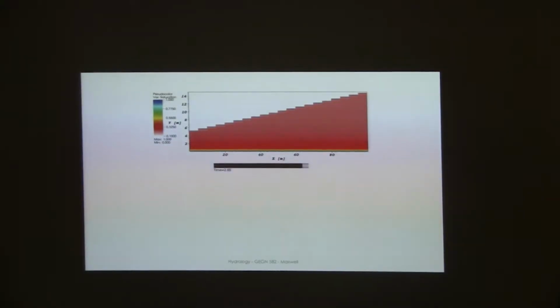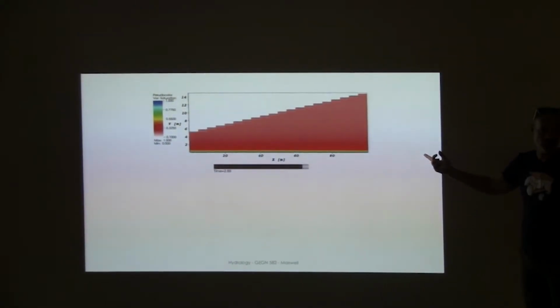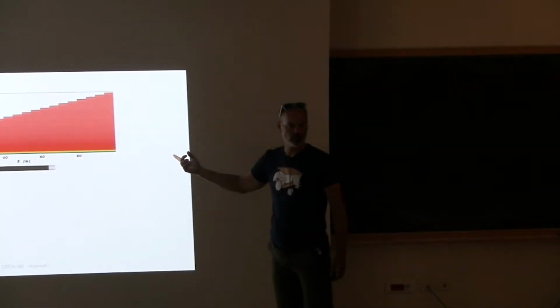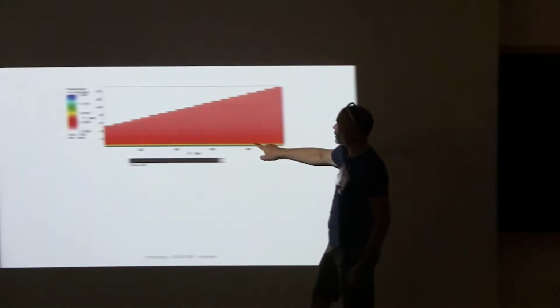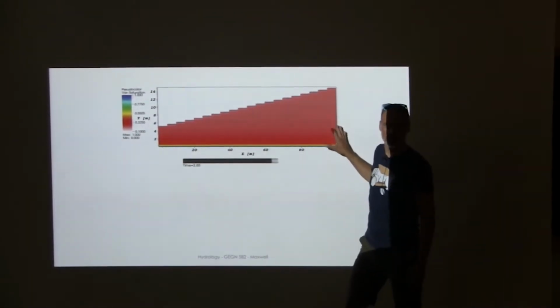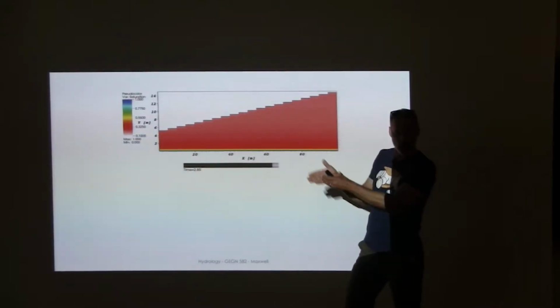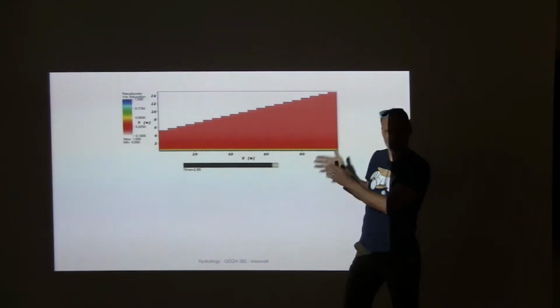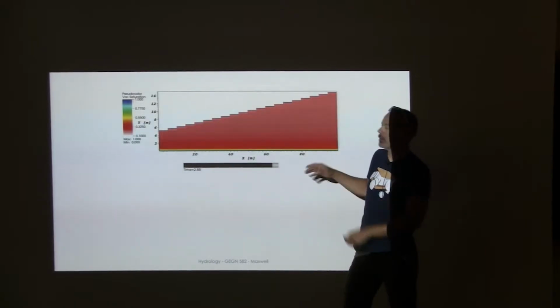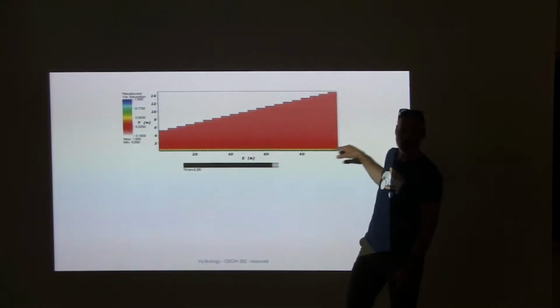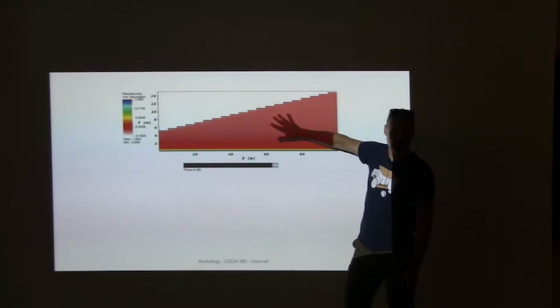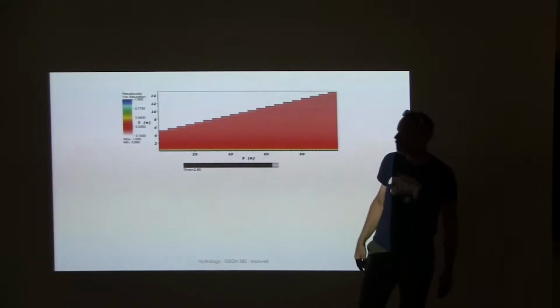It's a 1D model, no? You've got 2D things. This is a 2D hill slope. This is the model domain. But the only variable is X, no? Or do you model the water depth? This is saturation. So here's the water table, right? It's a 3D model. It's homogeneous over 2D. So it's effectively 2D, even though it's a 3D model. But we have ponding on the ground surface. We have a water table, very unsaturated conditions everywhere else. We just generate runoff from the top.